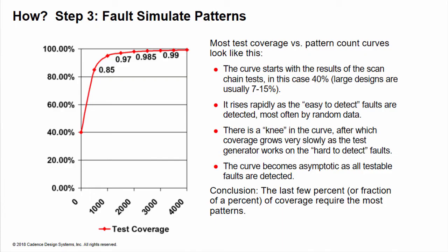There is an engineering trade-off here, where drastically reducing the number of test patterns, and therefore the cost of test, also reduces the coverage, but only a little. But system cost can build up rapidly, especially in complex systems due to test escapes. The length and slope of the tail are heavily affected by a number of factors. One that is under the control of the chip design team is how well they have followed the design rules. Compliance with the design rules will often have significant impact on chip quality, manufacturing test cost, system test cost, field returns, and customer satisfaction.